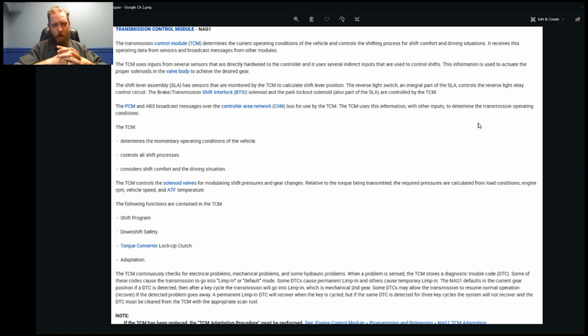And I started following along with the processes, but I was always confused when I was starting out as to how they were choosing the data PIDs that they were choosing to diagnose with and how they knew what good or what bad was. Because nobody can remember every data PID on every car and every spec and every variation on it.